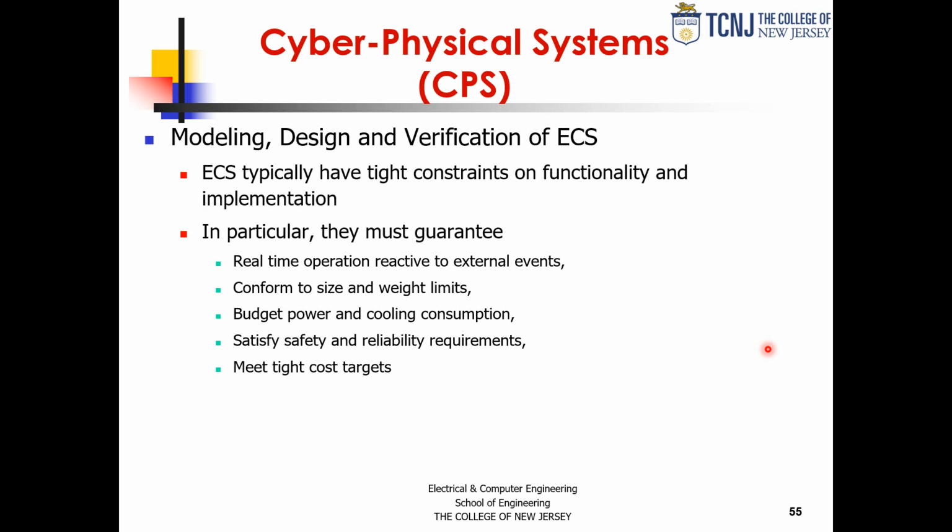A lot of them are operating on batteries, and because of the small physical spaces, they have very challenging power dissipation and cooling requirements. So the implication of dissipating a lot of power is that now you have to come up with a cooling mechanism if free air is not enough by convection.